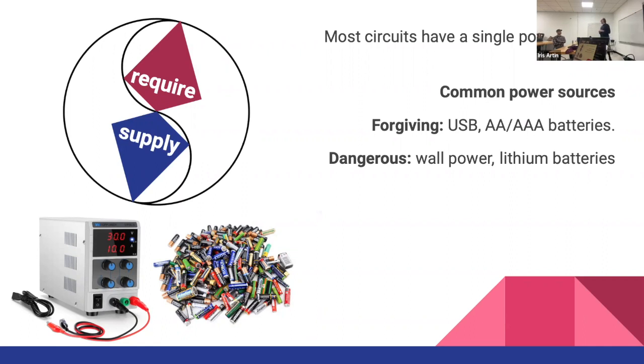And so if you look at hobby electronics, you will see a number of reputable vendors selling reasonable lithium batteries, and I would not say no to using those, because they have made sure that the batteries are good. They have also made sure that the battery contains a circuit that prevents it from being damaged in that particular way. But it is not as safe as using a AA or a AAA. And definitely I wouldn't pick up a random lithium battery that I found lying around and put it in something that I was building. Asking for a friend.